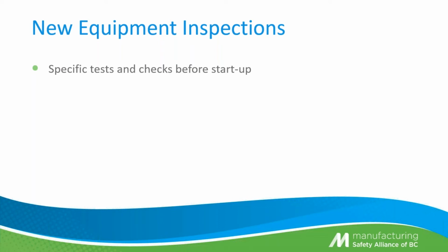One of my companies was making their own equipment. The downside of making your own equipment is you have to have it engineered. And even though they had it engineered out, it was missed that they had the wrong rated hydraulic lines. It wasn't until someone did a pre-check before they fired it up that they realized the hoses were rated at a lesser PSI, which means if they had put that press under full strain, it would easily have ruptured the hoses and potentially caused a serious accident. Just an example there.